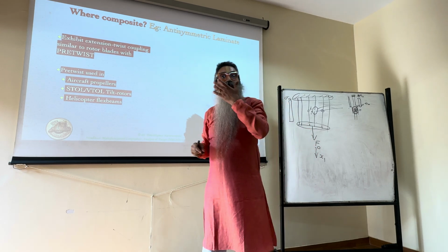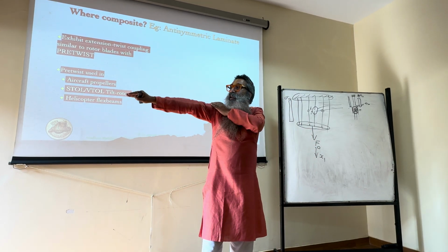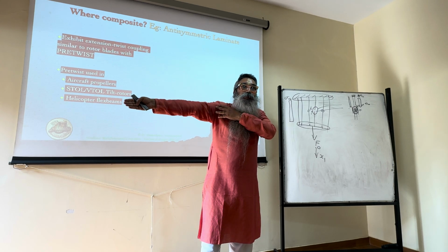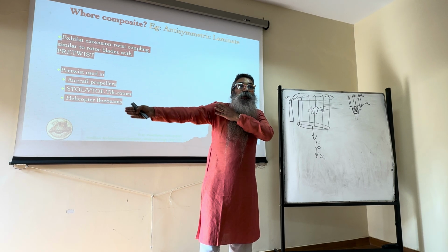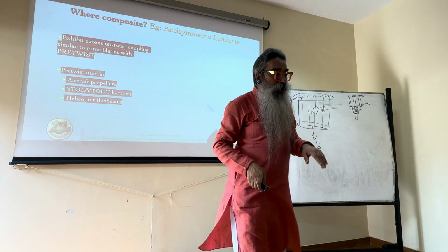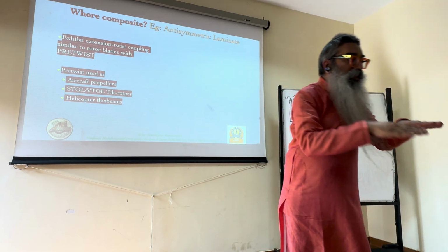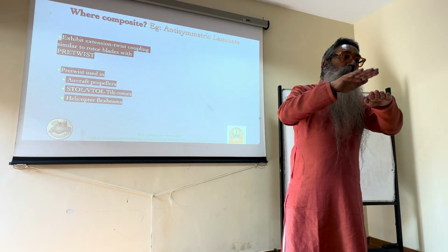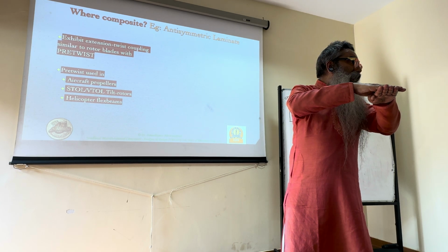Now, most of this was done by actually manufacturing these blades in a pre-twisted condition. So that's when no load is applied, this will be actually pre-twisted. But now with composites, you can have what is known as the antisymmetric layups. If one layer is plus theta, theta could be any value, I put another layer which is minus theta, right?